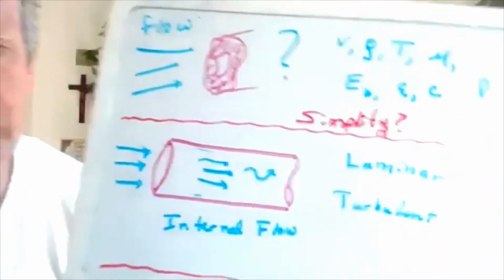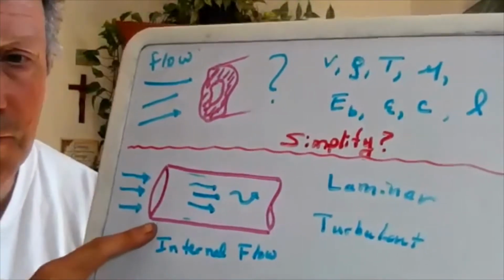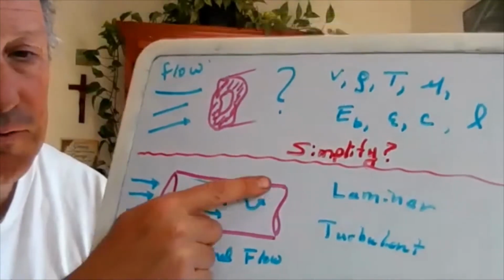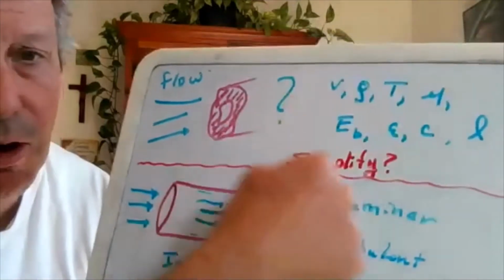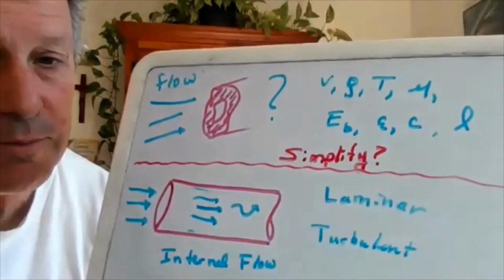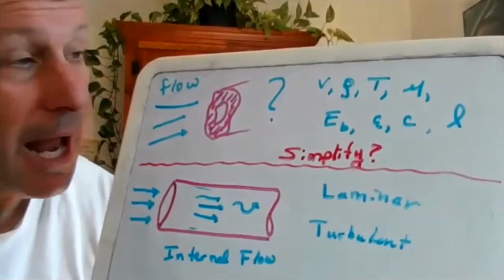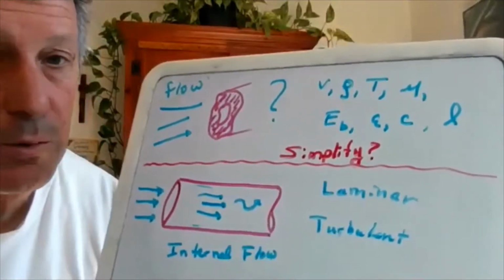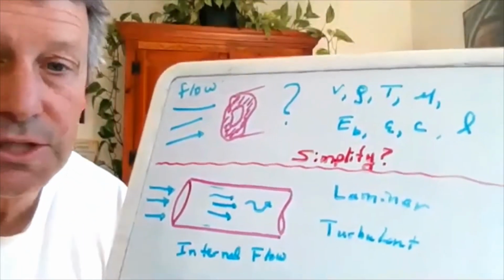And it turns out with this particular scenario, which is of course huge in engineering, where you have a pipe flow going through a pipe, that's one of your first decisions as your analysis: deciding laminar or turbulent. So you look up all this information here and try to put it together along with maybe the pipe diameter and some other information. And how are you going to decide on laminar or turbulent? Once again, it comes down to combining some of this information into a single parameter.